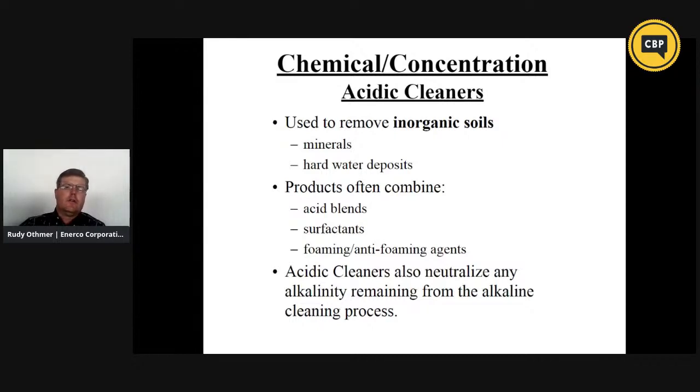The second reason, and not as big of a reason for our brewery folks, is the acidic cleaners also neutralize any residue left over from our alkaline cleaning process. Our 304 stainless steel in general very much desires to be in an acid state.